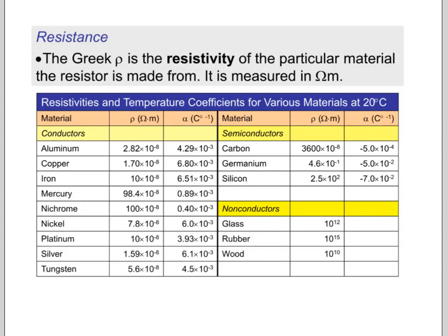So you would have to be given something like this. You can see the resistivity of these different metals. That would go into that little row in that previous equation. You'd need to know the cross-sectional diameter of the wire, which would lead to your cross-sectional area, and you'd need to know the length. And then you can calculate what the resistance of that wire would be.